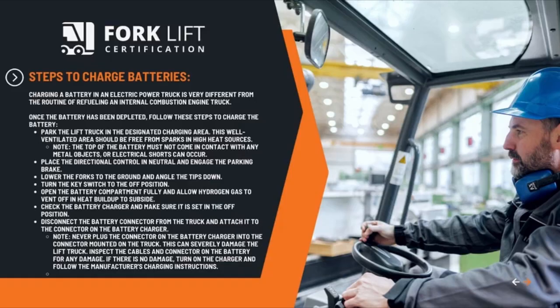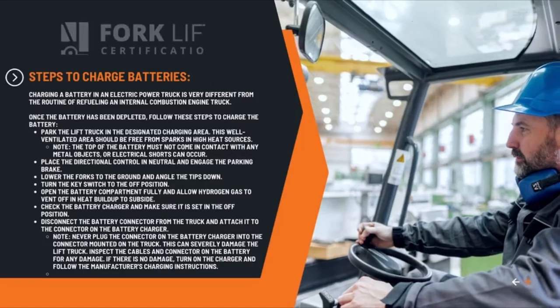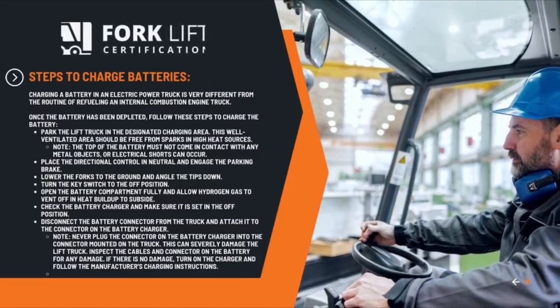Note, the top of the battery must not come in contact with any metal objects, or electrical shorts can occur. Place the directional control in neutral and engage the parking brake. Lower the forks to the ground and angle the tips down. Turn the key switch to the off position. Open the battery compartment fully and allow hydrogen gas to vent off and heat buildup to subside.